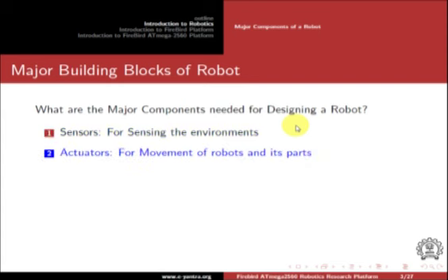Moving on to the next component, which is the actuator. Actuators in robotic system are analogous to human feet and hand, which help human being in locomotion and performing all sorts of tasks. In robot, actuators can be motors, which can be a DC or servo or stepper motor, or can be a hydraulic or pneumatic system, which help robot to move, pick objects and perform many other such tasks.